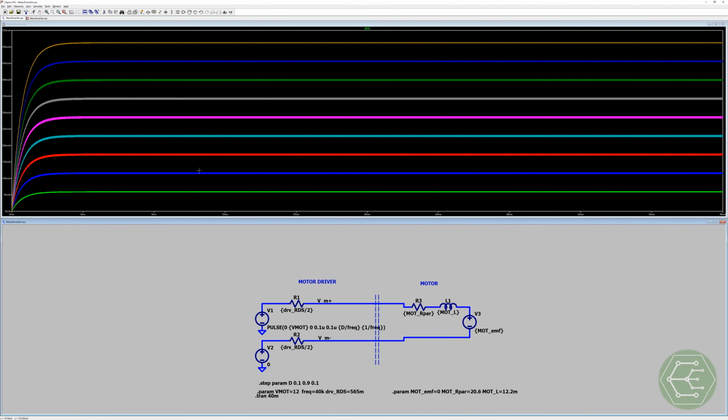It's not quite this extreme, right? I'm assuming that the motor is stalled. I'm assuming that someone is holding this motor. Absolutely cannot move. You're pushing against a brick wall. You never accelerate. So this would be like the maximum current at each of those set points. According to what we measured, we need to verify these measurements with some experimental stuff. Any model that's unverified will almost certainly have some glitches, whether it be an off-the-shelf SPICE model that you grabbed from a component vendor. I'd assume they did some testing to validate it, but you always have to validate a model, especially when it's one that you are creating.